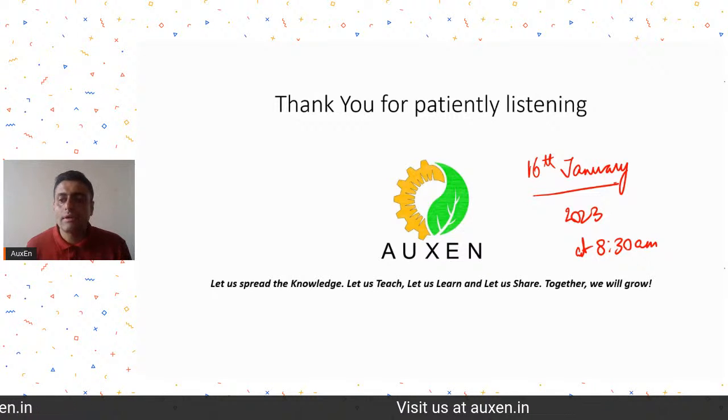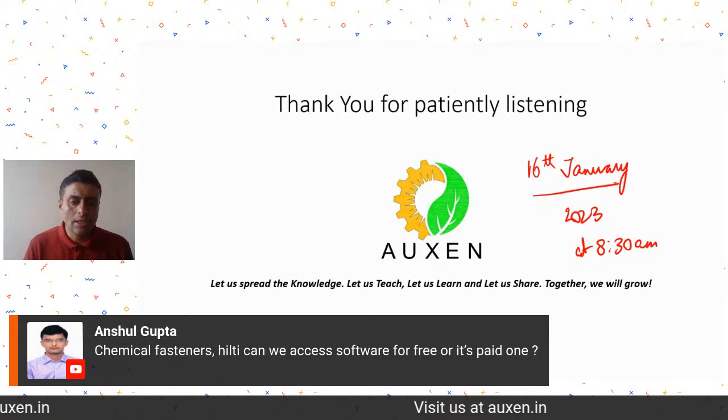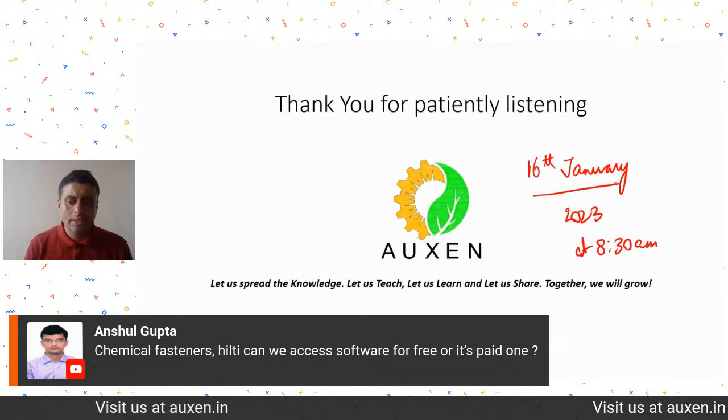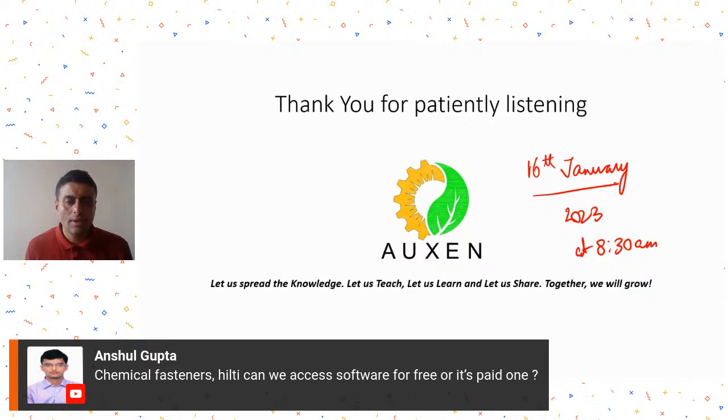Oh yes, I should have answered this. Let me just answer this question. So Anshul is saying chemical fasteners, Hilti. Yes, so I had mentioned the use of fasteners. Mostly fasteners mean that you have an existing RCC structure or any existing RCC member. On that, if you want to connect anything, then we have to put fasteners. And mainly these days, the fasteners that you get are chemical based. That means you put some adhesive chemicals, and then you put your fastener.